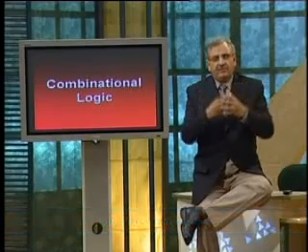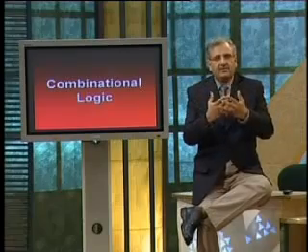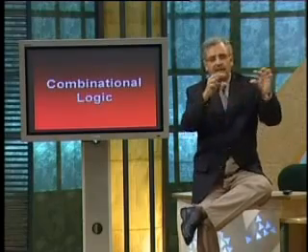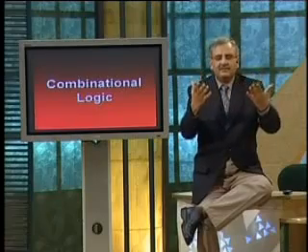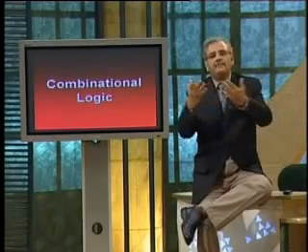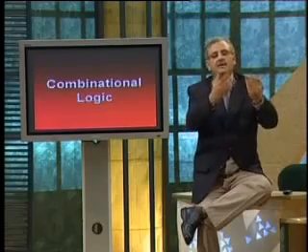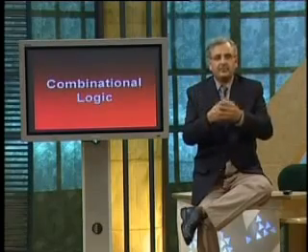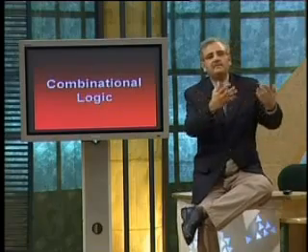Basically, the expression which represents a function is used to implement the circuit. So we have a Boolean expression which, let's say, represents the add function. We have a Boolean expression which represents the odd prime number checker circuit. We have an expression which represents the comparator circuit, and so on. The last step would be to implement these expressions using combinational logic or different gates combined together. Now, we have studied two forms of expressions, the sum of product form and the product of sum form.